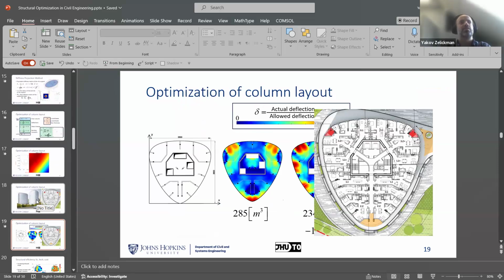But during excitations, you have mostly horizontal acceleration, right? Not only, but mostly. And this horizontal acceleration translates to horizontal forces that are then carried by the walls down to the foundations, because the walls have much higher horizontal stiffness.